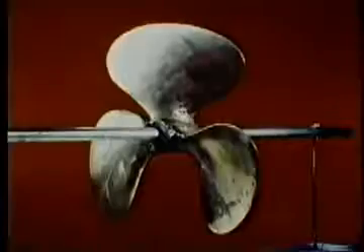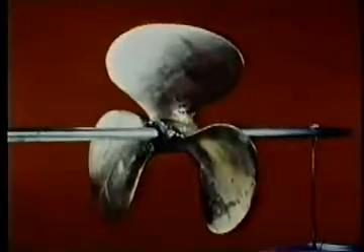The pressures associated with collapse are high enough to cause failure of metals. Here is cavitation damage on the runner of a large hydraulic turbine which operated under cavitating conditions for an extended period of time. This propeller operated under cavitating conditions for only a few days.